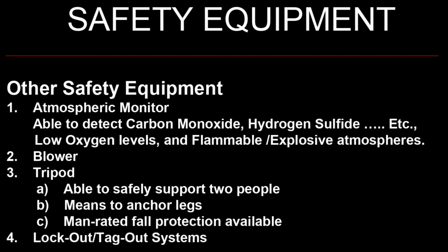Safety equipment. Other safety equipment. 1. Atmospheric monitor, able to detect carbon monoxide, hydrogen sulfide, etc., low oxygen levels, and flammable explosive atmospheres. 2. Blower. 3. Tripod: A. Able to safely support 2 people. B. Means to anchor legs. C. Man-rated fall protection available. 4. Lockout-tagout systems.